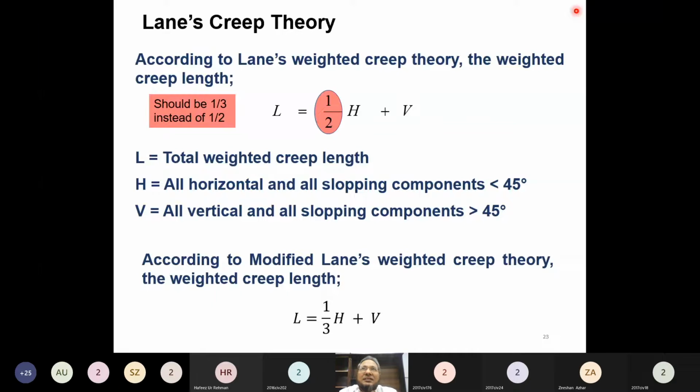Actually, the chapter is subsurface flow considerations for the design of barrage, and what we are discussing right now, the theory, is basically to consider the subsurface flow under the barrage. We know that when water flows under any hydraulic structure in the porous medium, it causes two problems.